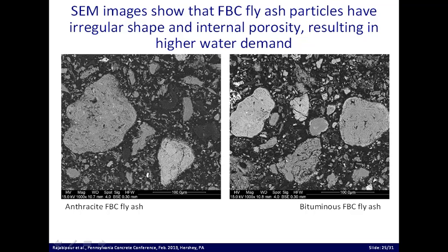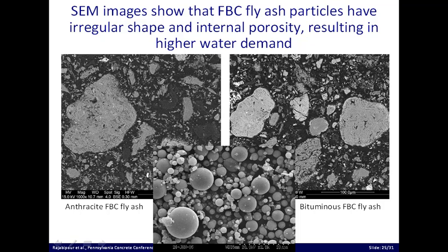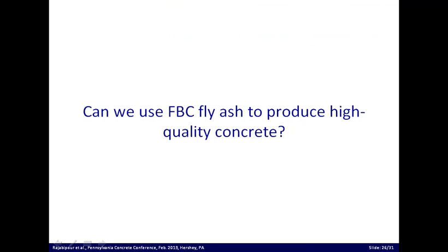We see again they have angular particles and internal porosity, and that can explain the higher water demand that we measured. And again, if we click, we see a comparison with nice solid spherical fly ashes without porosity, which usually had a lower water demand. Next slide, we want to see if we can use this to produce high quality concrete.